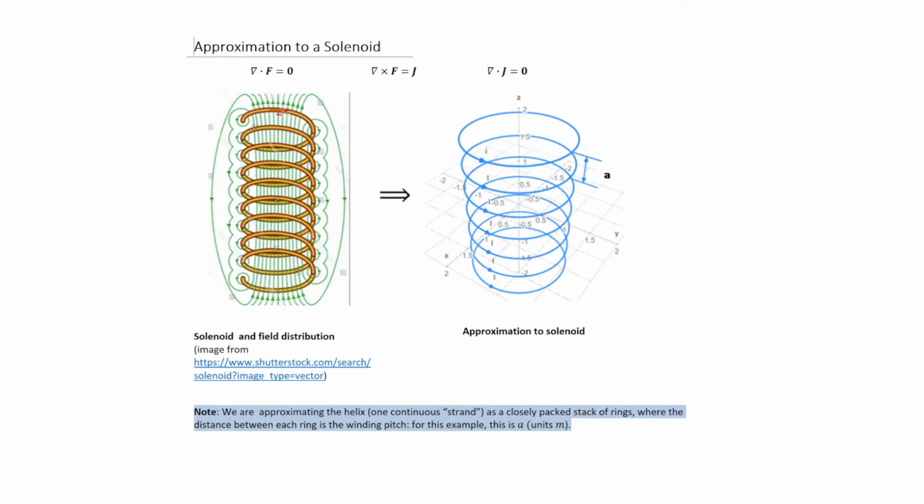All right, so let's start with a very simple picture to show how we make our life that much easier. This is an example of the actual solenoid that we're looking at, and the current is flowing around in this direction. Okay, so it's winding its way down. It appears that the current is flowing in an axial direction, but it is more or less a current with a larger component in a circumferential direction, as will be shown on your right-hand side. So using Stokes' theorem, we can determine what the direction of the field will be.